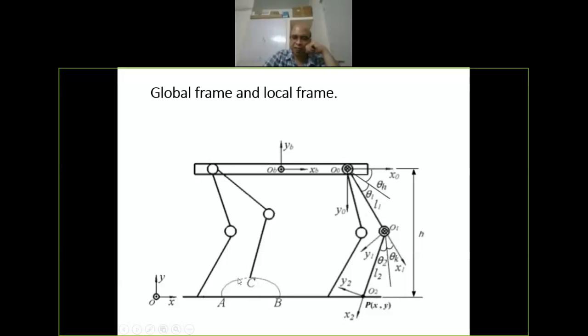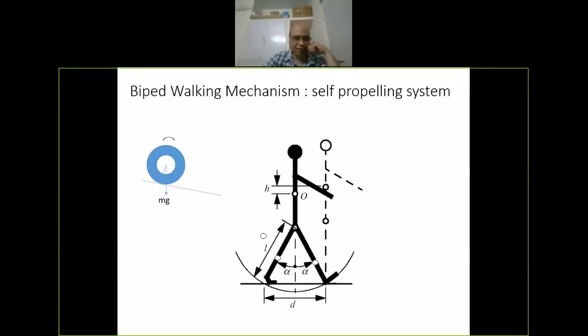So the leg which is in air follows a curve C, which takes it from point A to point B, and you can have multiple curves. The curve C can be of different types. It can have different heights. If you are considering this to be a spline, then the spline can have different A, B points and different C points. So you actually have infinite solutions. Now this problem has infinite solutions because it has more degrees of freedom than required to move the body forward. Okay, so this is the first thing we are seeing, that this is a redundant system, and we have multiple solutions of this problem.